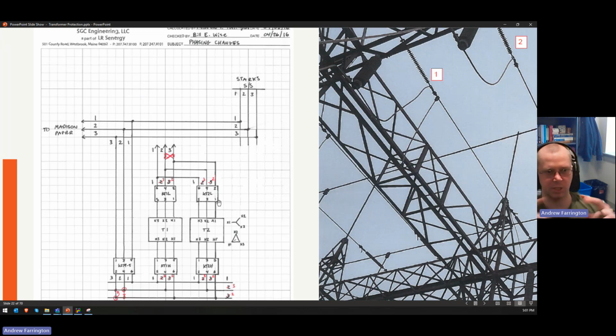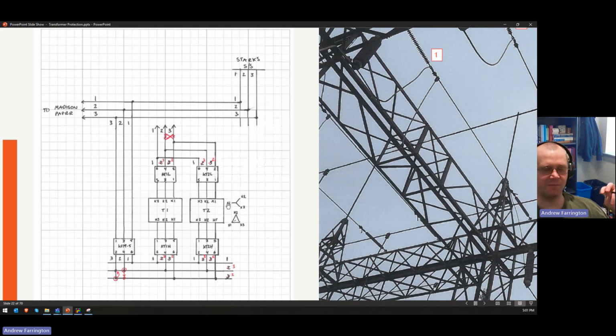So I said, well, can we change that rotation? And they said, no, it's weird. The phase tracker doesn't know what to do with it. We can't figure out why it doesn't work. And I said, I know what the problem is. So it turns out the phase shift for this transformer didn't match the phase shift for the local utility. So this really emphasizes a point I was trying to make, is that you've got to be paying attention to this, not only at the local substation,